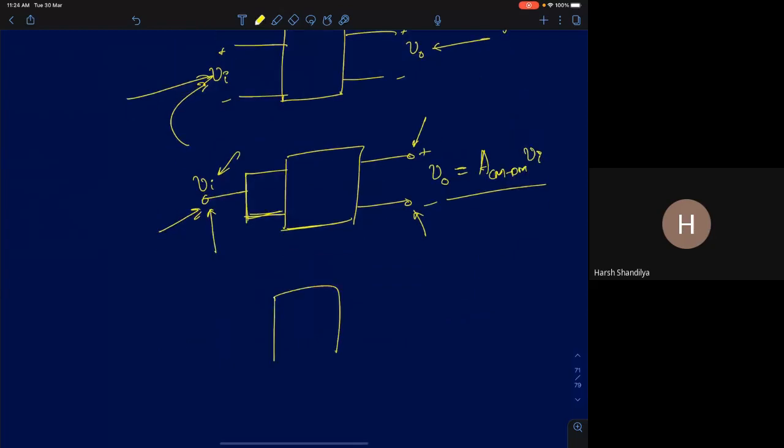That's how I measure ACM. So how do you measure ACM? You apply the same input to the differential amplifier and you short the outputs. That's like taking the average. So you're shorting the outputs and measuring it. That's how you measure ACM. Whereas ACM-DM is measured this way. You apply a common mode input, but measure the output differentially. So that will be ACM-DM times Vi.